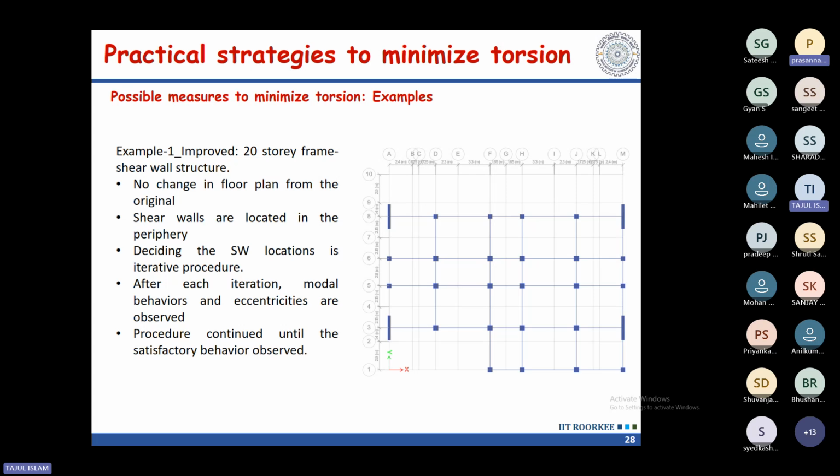I understood. What I mean to say is stiffness is a function of cross section and the length of the member. So it should not change irrespective of what element type you use. If it is changing, then there is something to look at in the model. So you should not rely on the software to virtually change the stiffness, because this is not going to happen in your actual structure. That you have to understand.